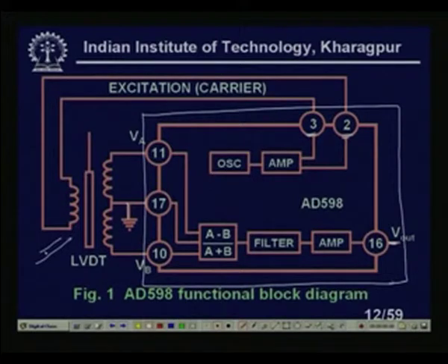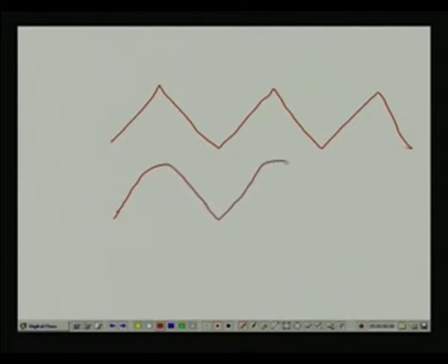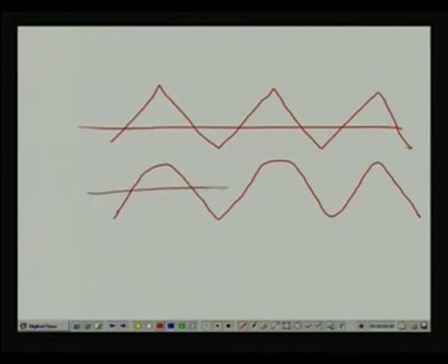Now, how do you do it? Triangular waves look like this. So, with a diode I can round off this value, so it will look like this. Though it is not exactly a sine wave, for most purposes it will suffice. It is a continuous form. There is error if you look at it, there are distortions, but it hardly matters, because nobody says that you have to use a sine wave there, right. And the frequency of this triangular wave, or the approximated sine wave, is determined by an external capacitor. Clear?